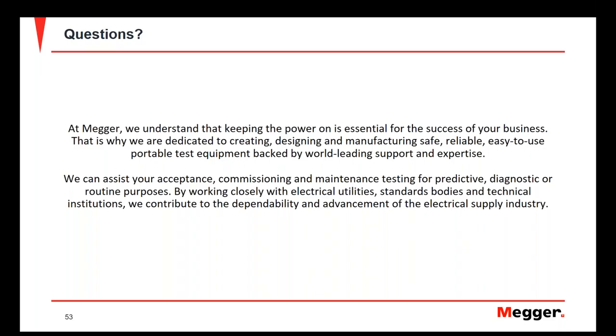The reason we have a separate test set for this particular application is because the primary injection test sets built to test regular circuit breakers are capable of injecting thousands of amps, a huge amount of current, but the output voltage, the load voltage or the open circuit voltage, is a very small number. It's usually just a few volts.